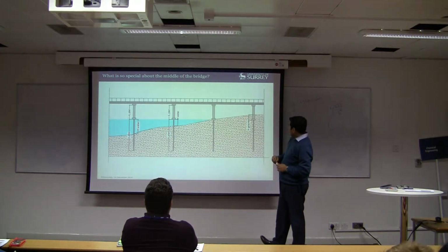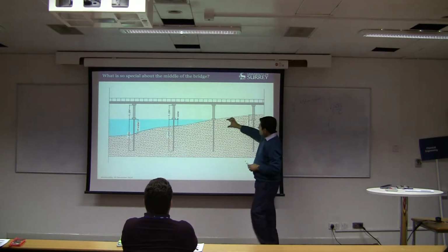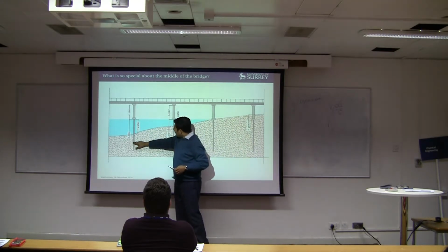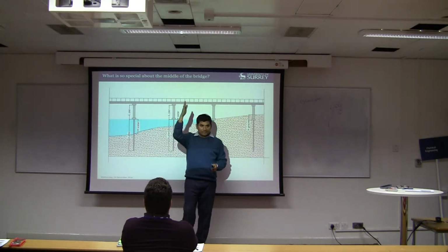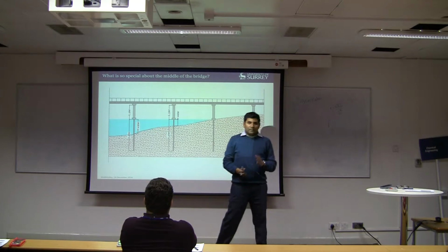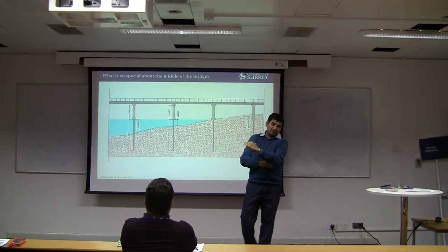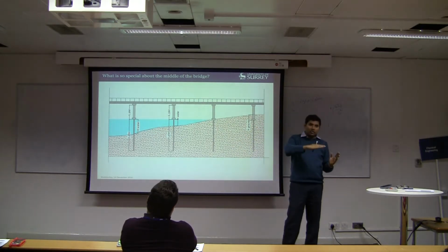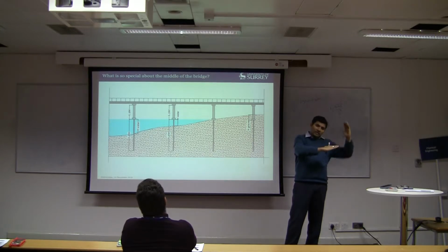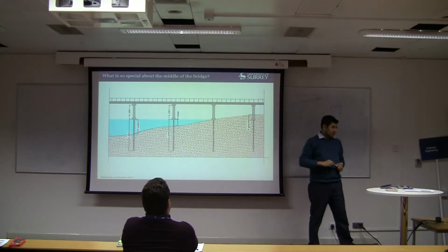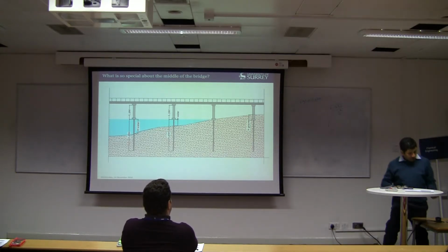When ground liquefies, it liquefies to a certain depth. So the middle part has more unsupported length. It then becomes more flexible, so it deforms more. As it deforms more, the depth falls. Right? That can be an explanation.